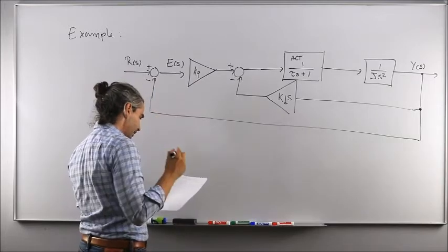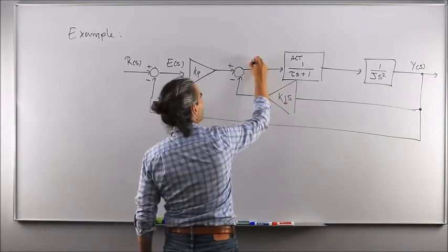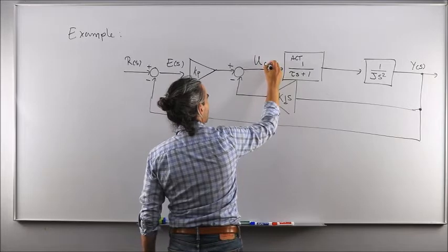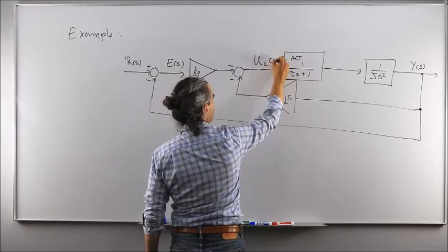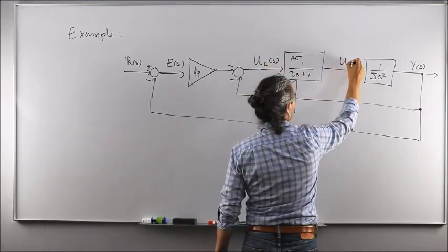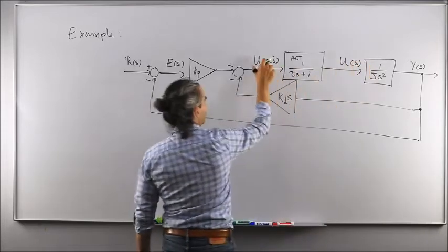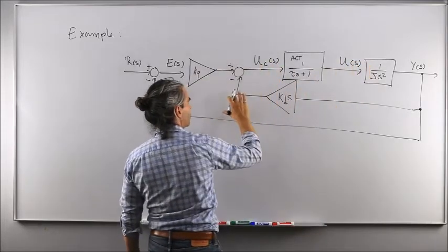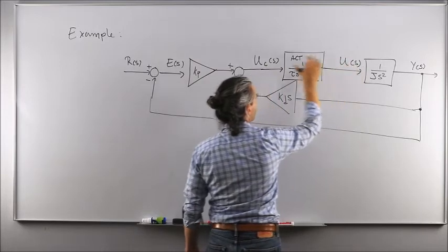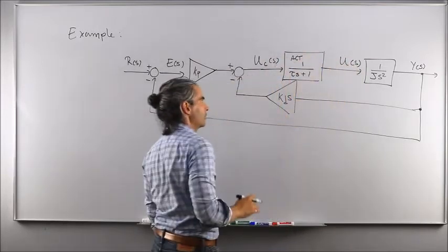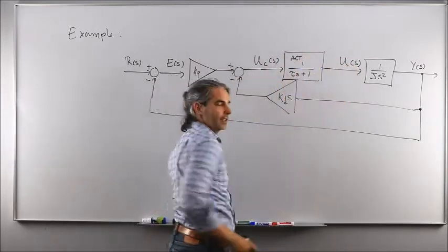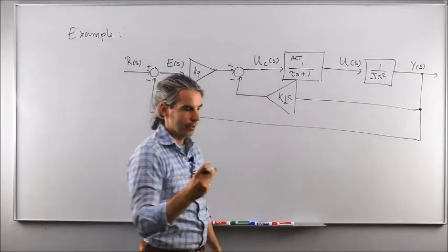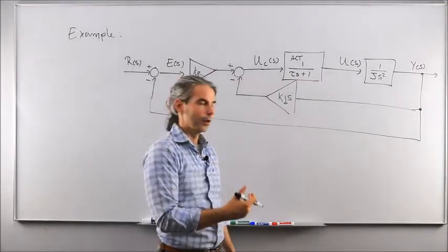So if you do the distinction now between the commanded control signal U and the applied one, or the desired torque as calculated by the controller and the applied torque, well, those two won't be equal to each other now because of this realistic mechanical device that doesn't respond instantaneously to what the controller wants.